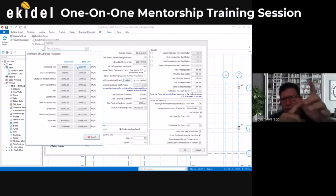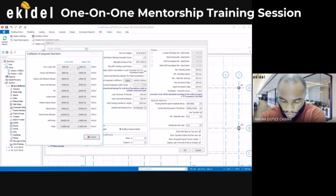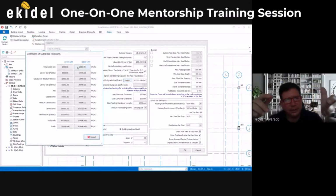And so we have to do friction piles. And then the other one is where we have coastal plains, which are a lot of swamp. So it's really silty, sandy clay or silt, where you don't really have any bearing capacity. So what we do, we drive these piles 30, 40 feet into the ground, and they're end bearing, directly on bedrock. And this kind of bedrock is an old weathered limestone.